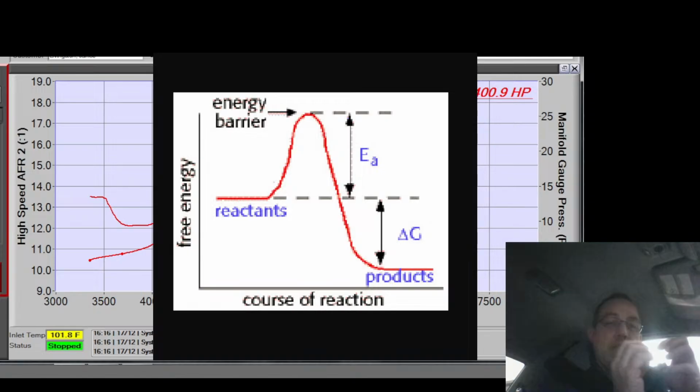But anyways, the point is that the energy in there has to be able to transfer from the one set of burning molecules to the next one, right? It has to be able to propagate in the cylinder. And it does that by giving enough energy that it breaks over this activation energy so the next one can ignite. So if I have a larger gap, then like I discussed earlier, I need more energy to cross that gap. And if I pack a bunch of molecules in between there, I need even more energy to ionize all the molecules in that little chain.